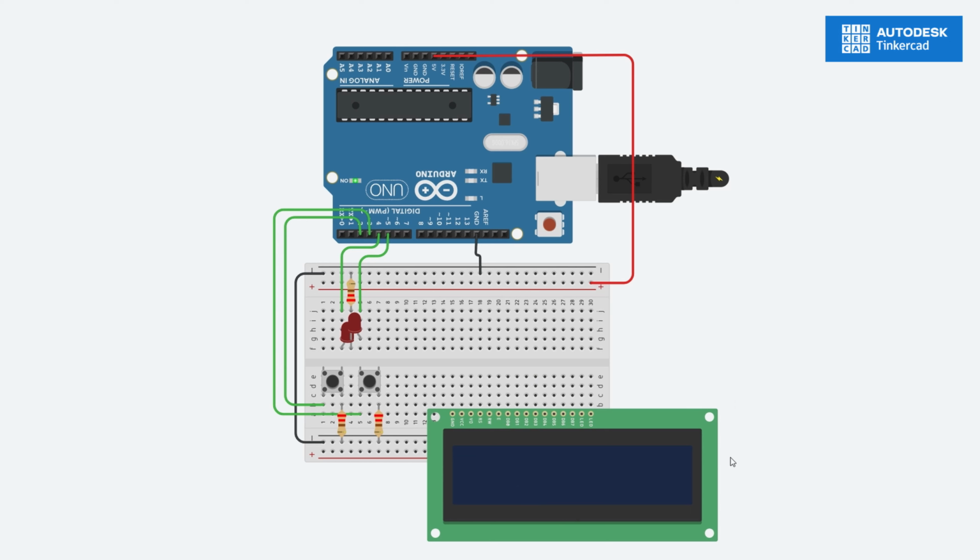So of course you won't see anything on the LCD display yet, but we only want to see if the buttons light up. The left LED lit up when I press the left button, as well as the right button lights up the right LED. So that's functionally perfect. Next we'll add the potentiometer, which will connect to ground as well as to the 5-volt input that we have. Now we'll start connecting our LCD display.